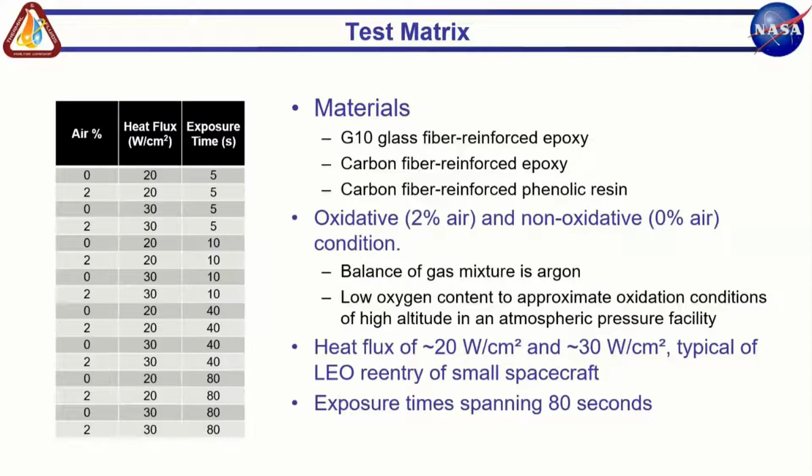And this low air mixture was meant to approximate the oxidation conditions of high altitude, even though the facility itself is at atmospheric pressure. And then we tested 2 different heat fluxes and exposure times from 5 to 80 seconds to cover the full range of expected heat pulse times for a low Earth orbit reentry.